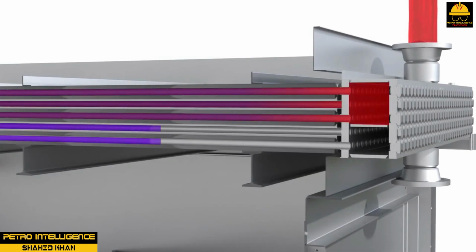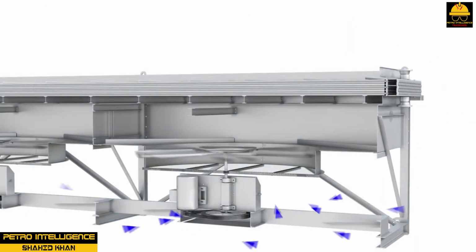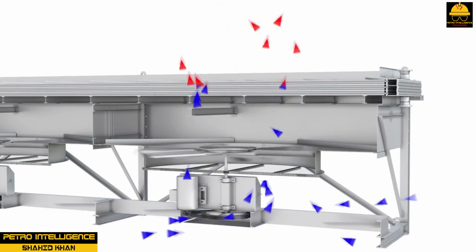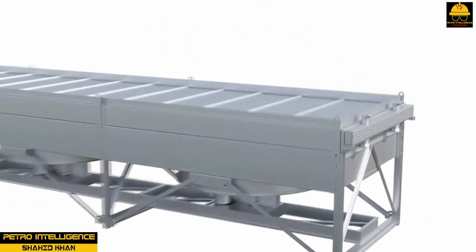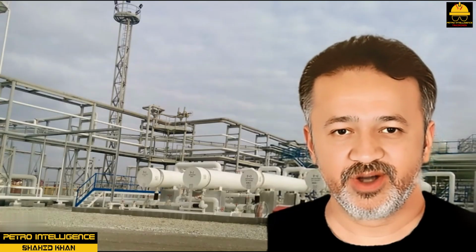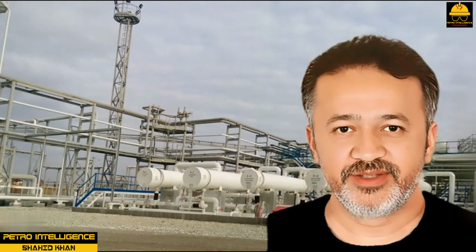Aluminum blades are designed to operate in temperatures up to 300 degrees Fahrenheit or 148.88 degrees Celsius, whereas plastic blades are limited to air temperatures between 160 degrees Fahrenheit and 180 degrees Fahrenheit, or 71.11 degrees Celsius to 82.22 degrees Celsius. Air-cooled heat exchangers can be found in service on air compressors, in recirculation systems, and in condensing operations. This type of heat transfer device provides a 40 degrees Fahrenheit or 4.44 degrees Celsius temperature differential between the ambient air and the exiting process fluid.